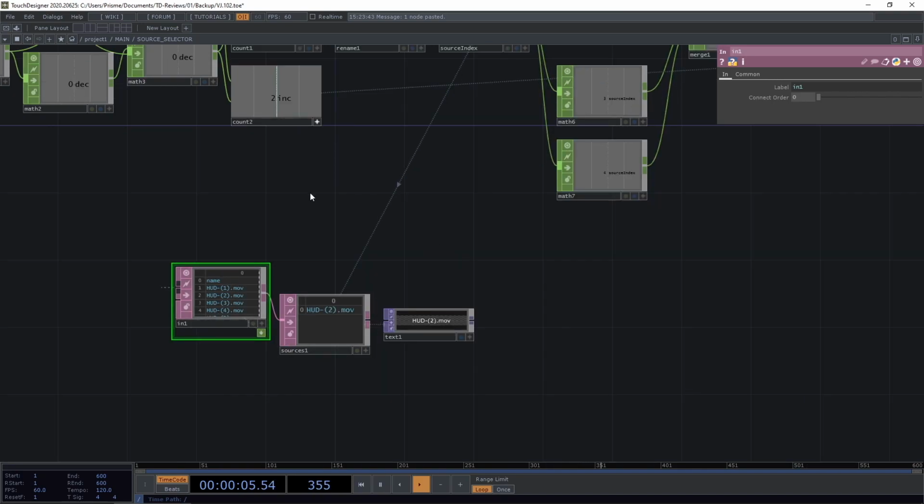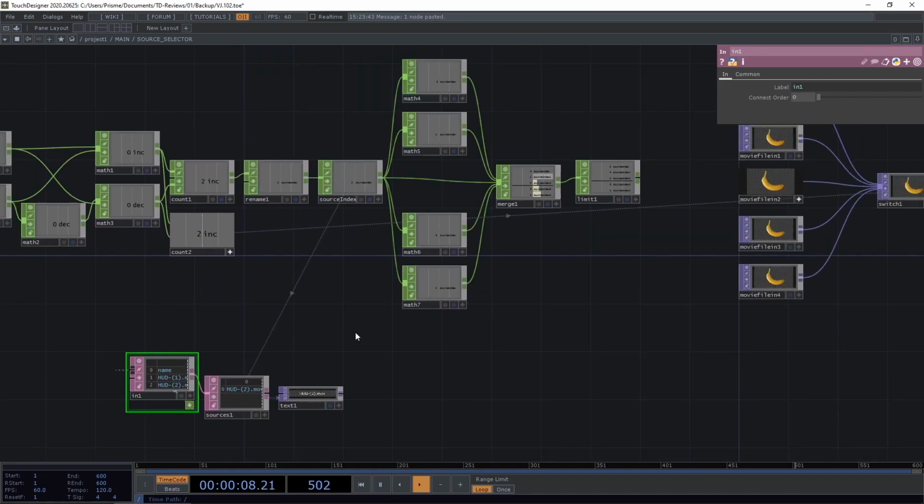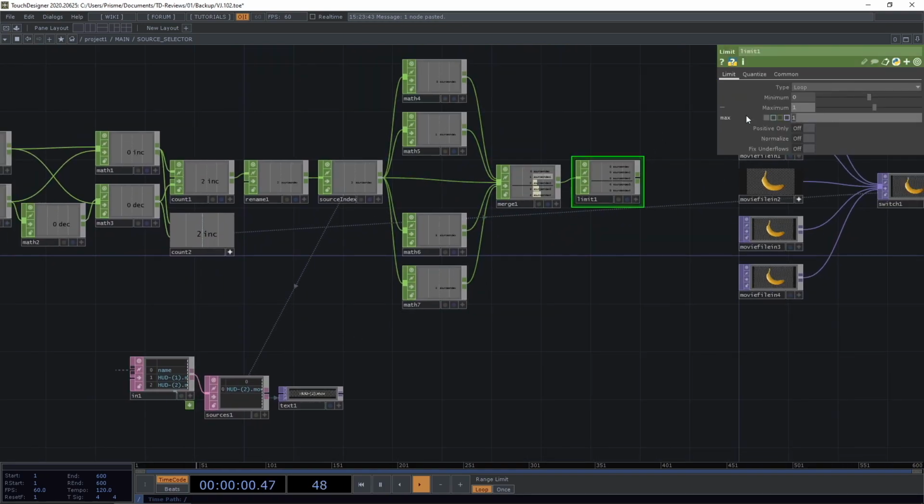So to access the number of available rows here, we're gonna use a little bit of Python. For this, I'm gonna start by selecting this node, so that's OP, and the node is named input1, so IM1, and I'm gonna select one of its properties, which is num rows, if I'm not mistaken, and just because this number says the number of rows and not the number of the last row, we have to do a -1 to be sure it's the correct value.